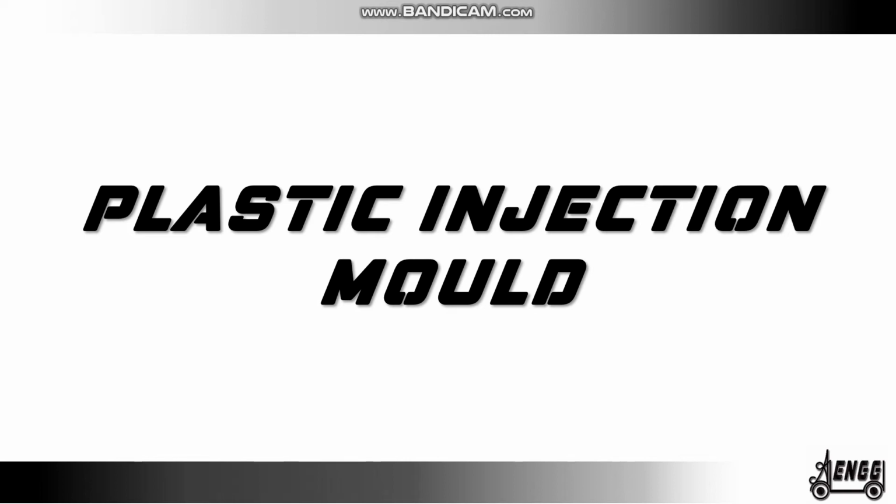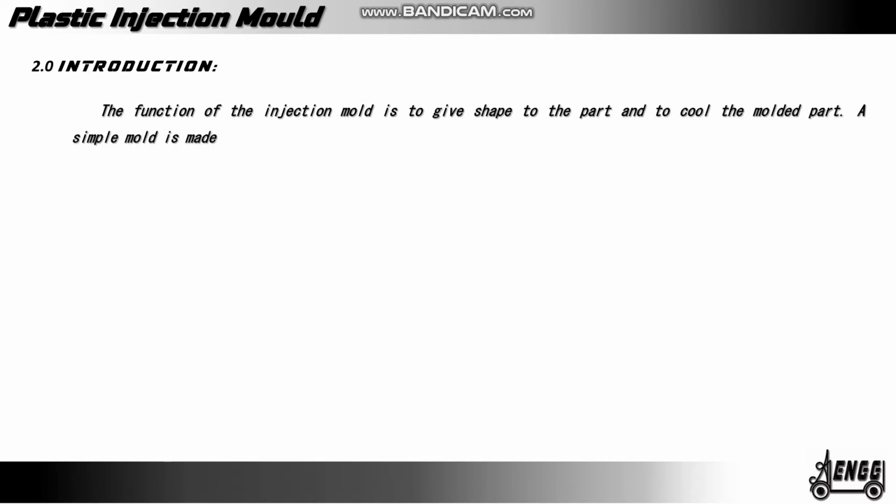Today I would like to discuss with you plastic injection molds under mold technology. Introduction. The function of the injection mold is to give shape to the part and to cool the molded part. A simple mold is made up of two components: the cavity and the core.